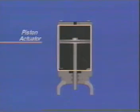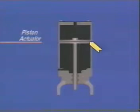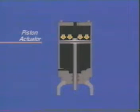Looking at this drawing, you can see that the actuator is simply a piston that slides within a cylinder. A seal is provided between the piston and cylinder by piston rings. This seal, which may be as simple as an O-ring, adds to the force the actuator must overcome when positioning the valve. As with a diaphragm actuator, there are opposing forces acting on the piston that are controlled to obtain the desired positioning. In a direct-acting piston, actuating air applies force in this direction. The opposing force is often provided by a fixed or static air pressure that acts as an air spring.